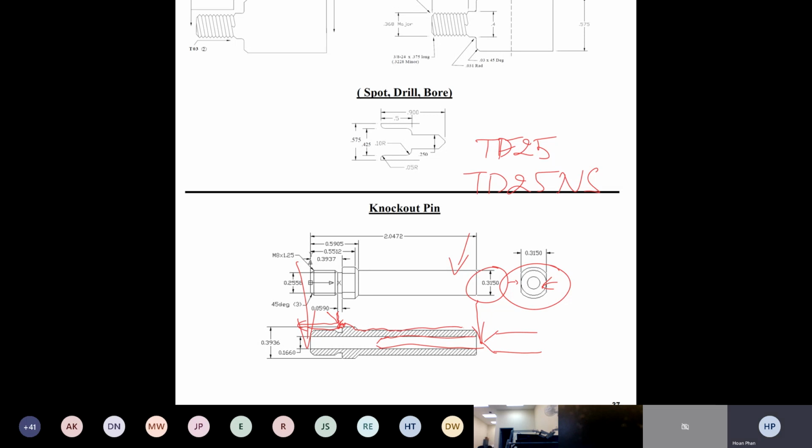Okay, so we need to plan to get the pickup collet right here for this side, in order to have it come in with the sub spindle and pick it up. So we can pick it up all the way to this point right here. So what is gonna be left for the sub spindle? Okay, we planned to drill just 2/3 of the part, so on the back side we still have to drill it. We're gonna have the left hand boring bar in order to do facing, and then turn the section right here.